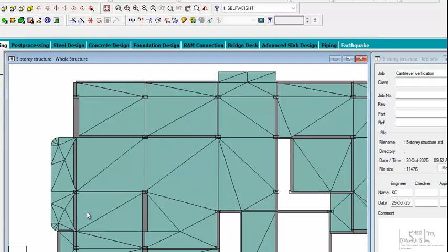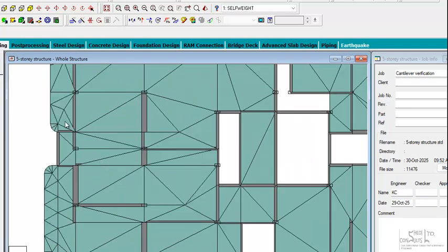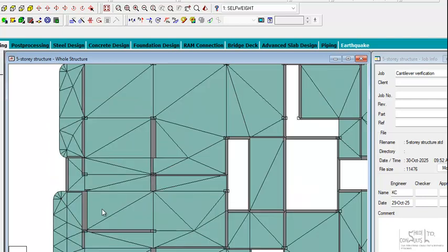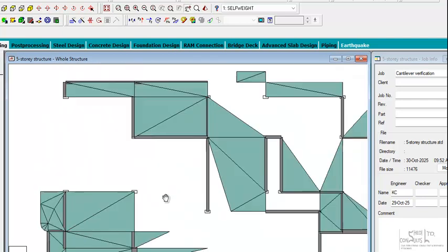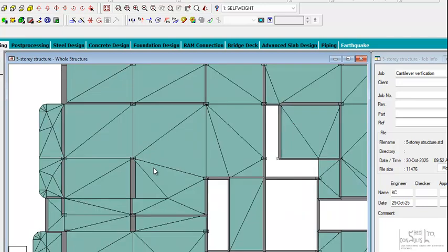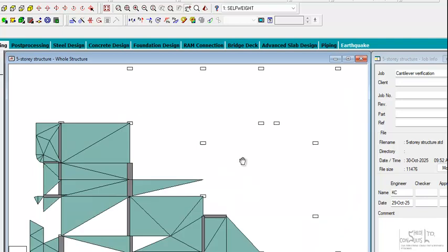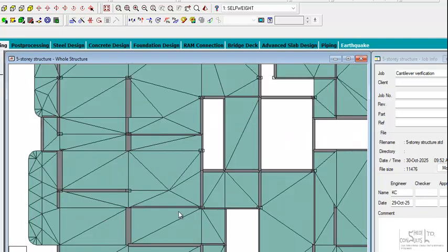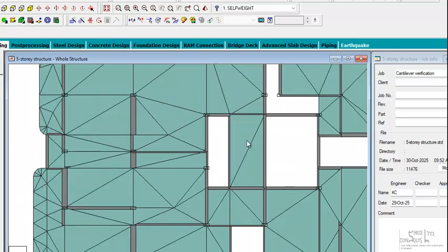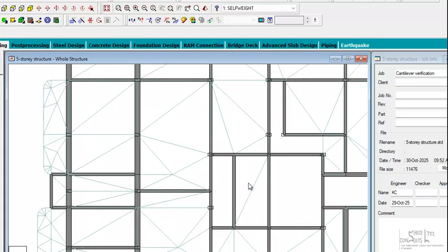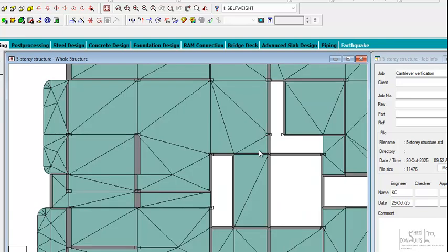My concern now is to verify the cantilever requirements for the slab at the west side of the building to ensure that the thickness, the deflection of the cantilever during construction and post-construction meets the code requirements. So what I did was to model the entire first floor structural layout, as you can see on the screen, using the information provided on the structural drawing.